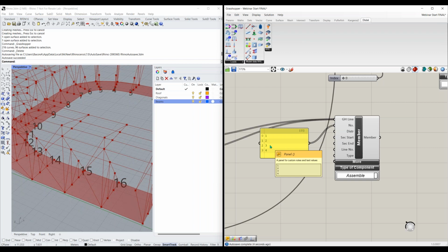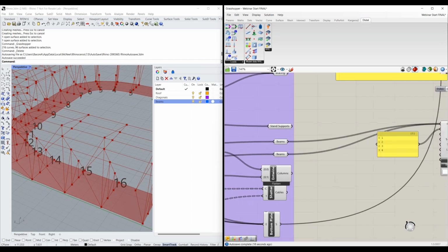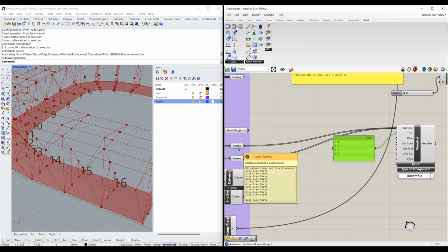But the problem when it comes to this is that you're going to need one ID for each line, because from each line we create one member. So we have about 32 lines from our geometry over here. So manually creating 32 list numbers in here isn't really the best idea. And also the bigger issue is that this model is parametric. And so I would have to rework this list every single time my model changes over here, whenever I change my model parameters.